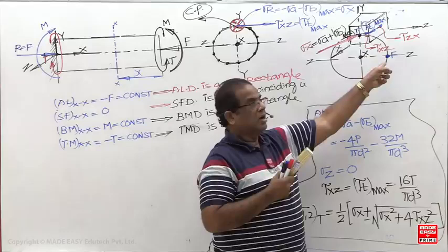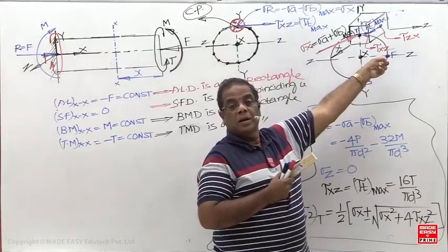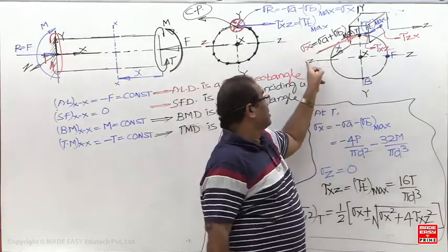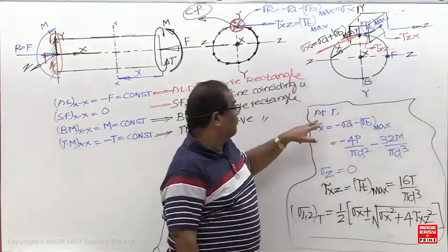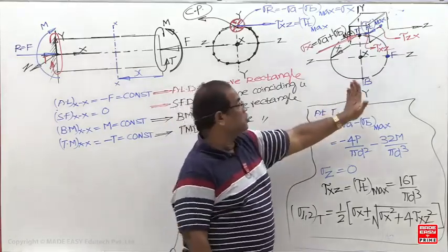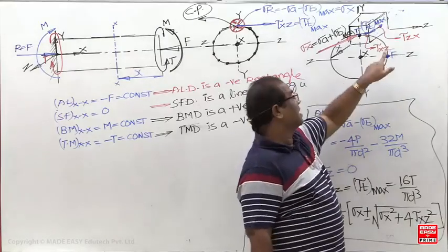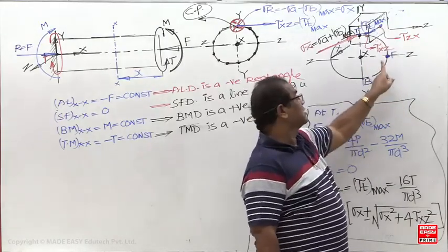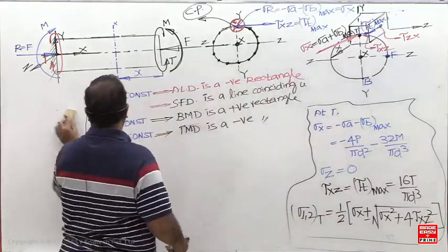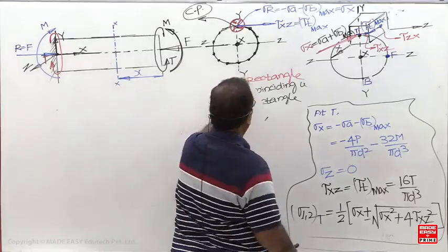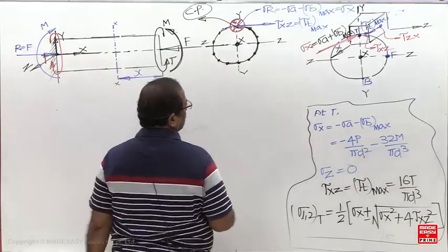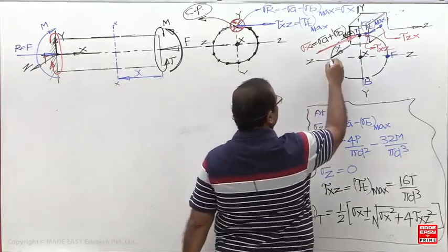If we ask about F, it is on the horizontal centroidal axis, a vertical bending. Under vertical bending, this will become the neutral axis, so bending stress is 0. So at F, sigma x equals minus sigma A, sigma y is 0. Torsional shear stress becomes tau xy, so I have to consider the X and Y plane.